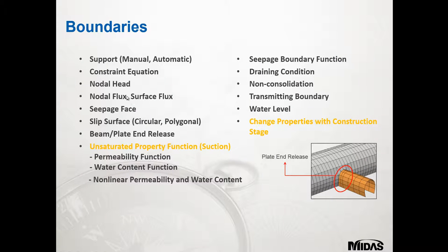Just a few boundary conditions, some simple ones in the form of supports. We've got the constraint equation, nodal flux and surface flux, which are your water conditions, and seepage face. We can also look at the slip surface, circular or polygonal, and the unsaturated property function in the form of suction and heave. We can look at the consolidation and the draining conditions as well. We can even look at the change of properties with construction stages.